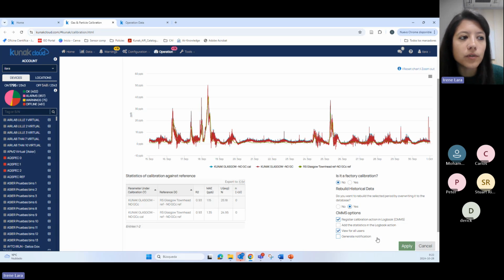So we recommend doing, for example, a baseline calibration when the average temperature changes more than 10 degrees. That means we recommend doing this baseline calibration once per season. So probably if you are calibrating your baseline in September, it won't be good for a calibration for a period in June. It depends also on the location and the seasons, but probably it won't be good.